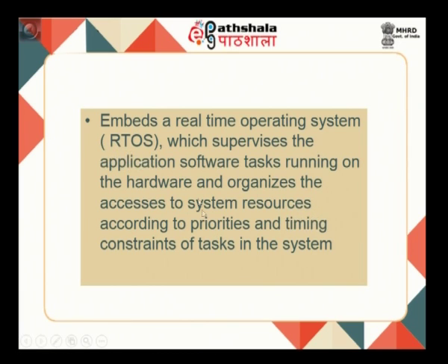So, the basic difference between your normal OS and this real time operating system is that it schedules the tasks with priorities, whether it may be a static priority or a dynamic priority. What I am trying to say here is, with static priority, whatever job it will be running will be scheduled with already fixed priorities, maybe process 1 is the topmost priority, process 4 is the least priority.